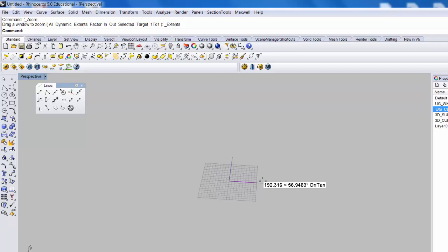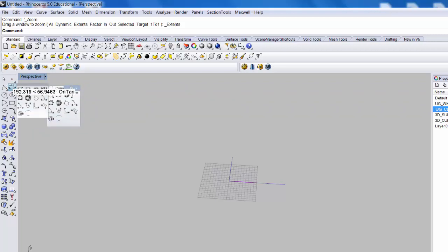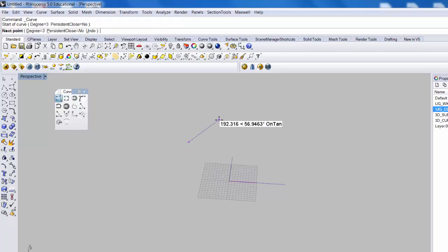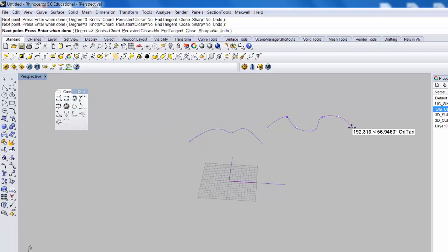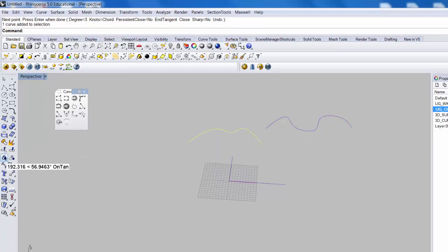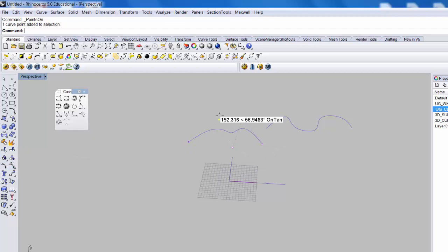The curves, so polyline curves, two different basics you want to know about curves. And all I'm doing to get these things to hang out is holding down the button, and then I can drag that off. So a control point curve is, I'm going to click points out in space, but it's not going to go through those points. So these are control points that are then controlling the shape of that curve. An interpolated curve is actually going to go right through those points. See the difference? That's useful to know because when I pick the control point curve, I can edit by clicking those points that I actually picked.